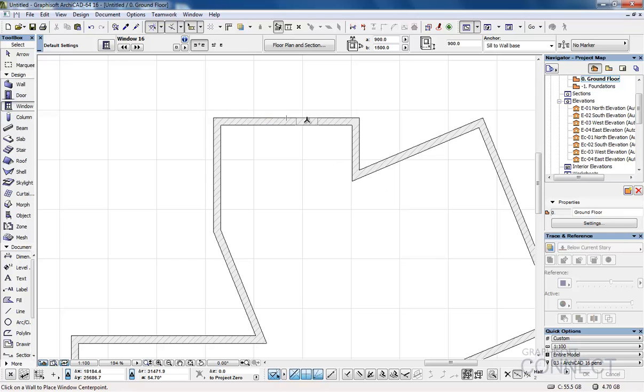It's actually controlled down here, and currently it's set for half across a full length element. All I need to do is put the mouse on the edge of a wall. You'll see that automatically a little preview appears, so I can see where this window is going to be placed. So if I put it in any wall, you'll see as I highlight the wall, the preview appears. And all I'm going to do is take the mouse to the centre of this wall, and you'll see a little marker appears where I get a tick. This means I'm exactly in the middle of the wall, and I can just click the mouse. That places the centre of the window. Click outside, and my window's in place.